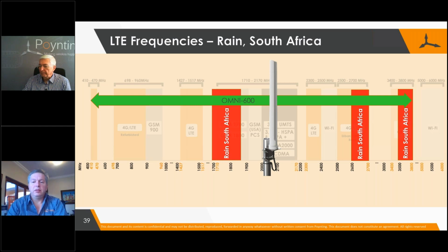Stephen? Peter, just to make a quick comment over here, is that as you check sites like Cell Mapper or Frequency Check, it's always good to just read up and research, because the networks might be experimenting with new frequency bands. And for that, it's good to look at an antenna that's also more future-proof, so that if you do change from one network to another network, or that specific network brings out new frequency bands, then your antenna, which is already installed, is capable of those frequencies, rather than just looking at Cell Mapper and selecting only those frequency bands.